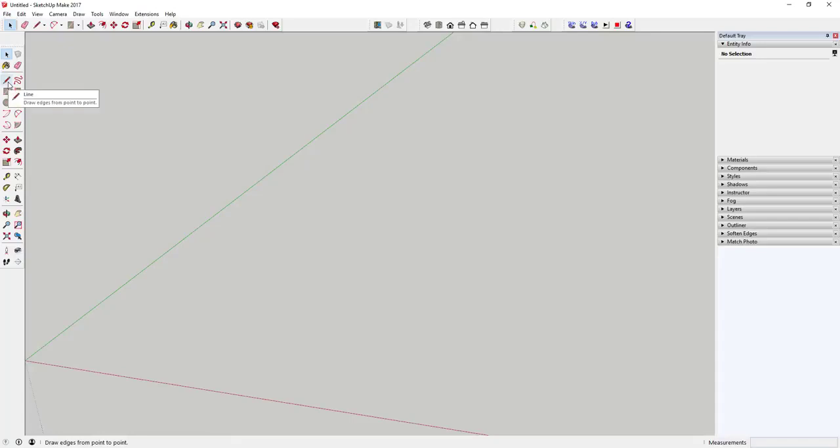All of your different tools in SketchUp have different inputs, and we're going to start off very basic with the line tool. If you come over here and click on the line tool, this allows you to draw a line in SketchUp. If you look down here, when I activated the line tool, there's an instruction: select your start point. That's telling you what to do with your current object. And then once I click, it now says select endpoint or enter value.